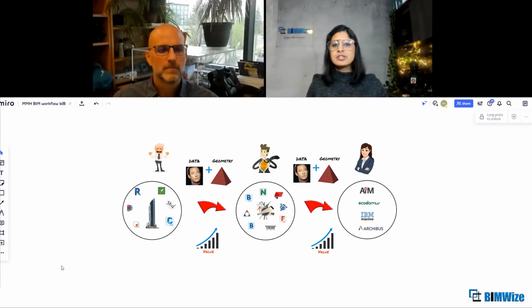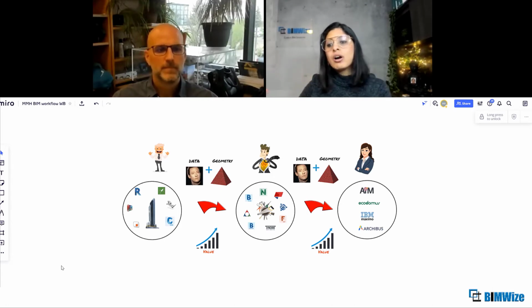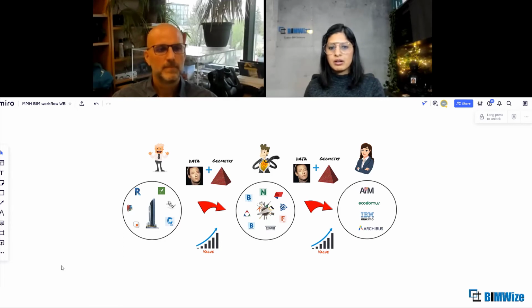As designers, as contractors, we need to know where we have to stop putting in information, where an architect or an engineer stops their work and gives that to the contractor, or the contractor gives that to trades, that this is where your scope begins. So if we do not define LOD, or we just leave it vague, how would somebody know, especially on the design side, that this is where we need to stop putting in information?